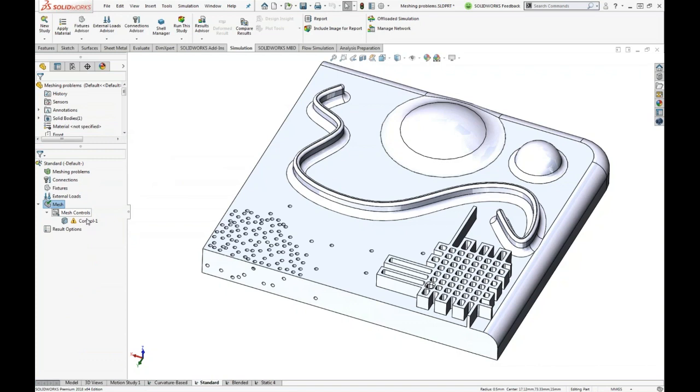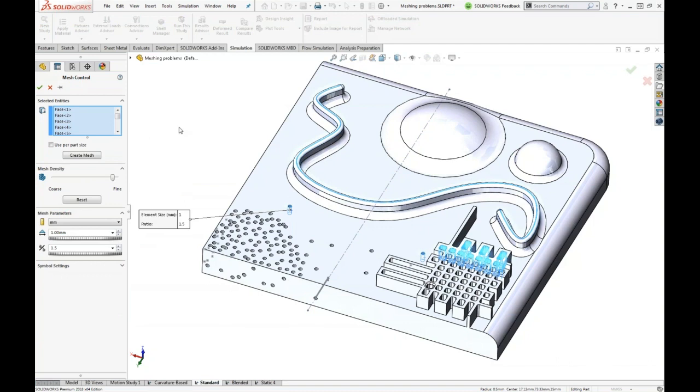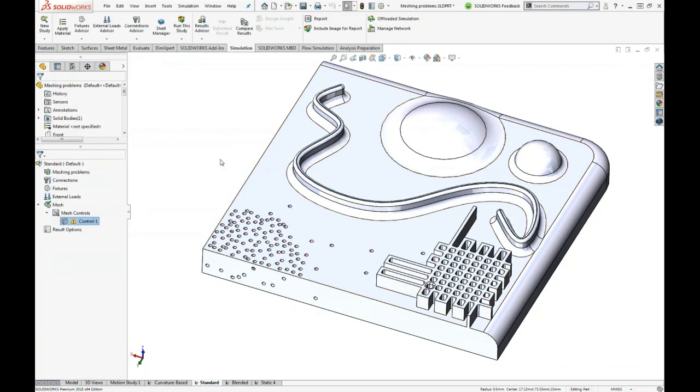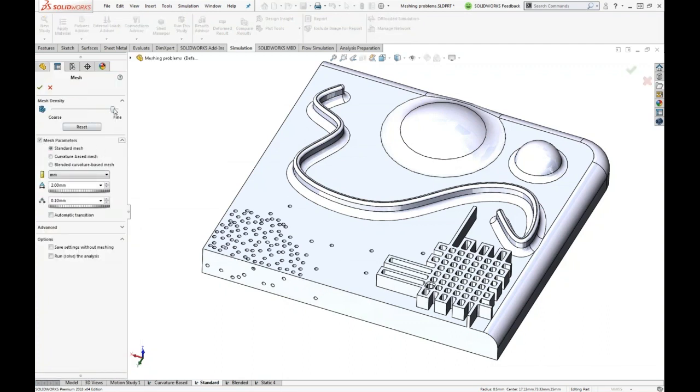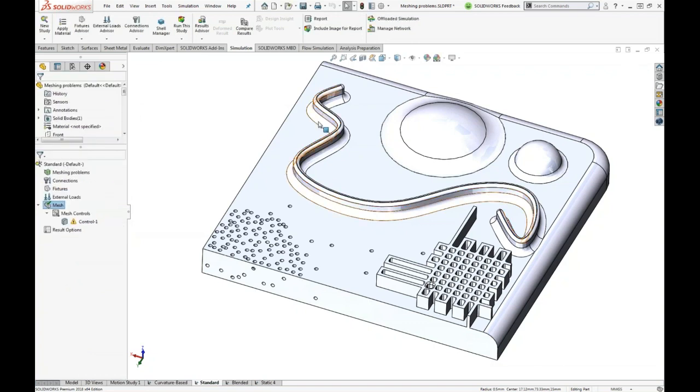In order to get a valid mesh on this model, I had to manually go through with trial and error and apply a local mesh refinement to 133 unique faces. I also had to manipulate the global size down a bit smaller just to even get it to fire, to a 2 millimeter general size. But I got it done.